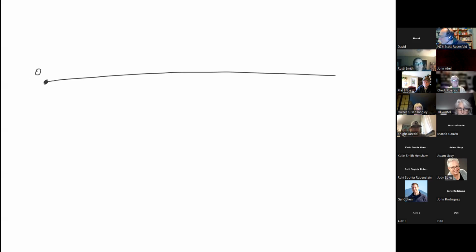So what does it have to be at the other end? Zero. It has to be zero. So this is an important thing to remember. Typically, unless there's a corona, unless there's lightning coming off of it, the current at the end of a piece of wire is zero. Okay? So now, I'm going to just start drawing a wave.